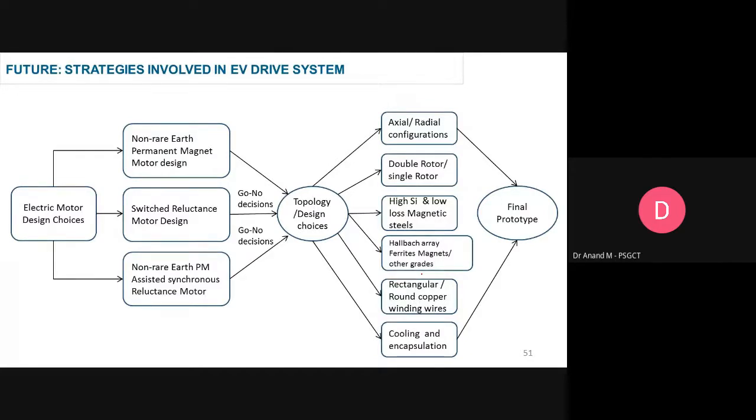The encapsulation is nothing but, as we could see even in recent e-vehicles, if you see the anatomy of the electromagnetic system, it is completely encapsulated, where the rotor slots, the stator slots and the stator windings are not exposed, completely immersed and encapsulated by the use of high temperature resistant potting. Maybe the temperature comes into the picture. We can think about the magnet with a low ambient temperature, but with the encapsulating condition, it will be a better choice for the EV system.